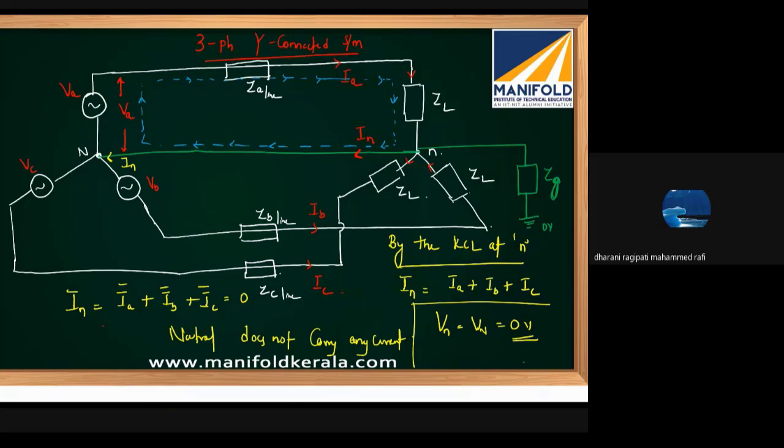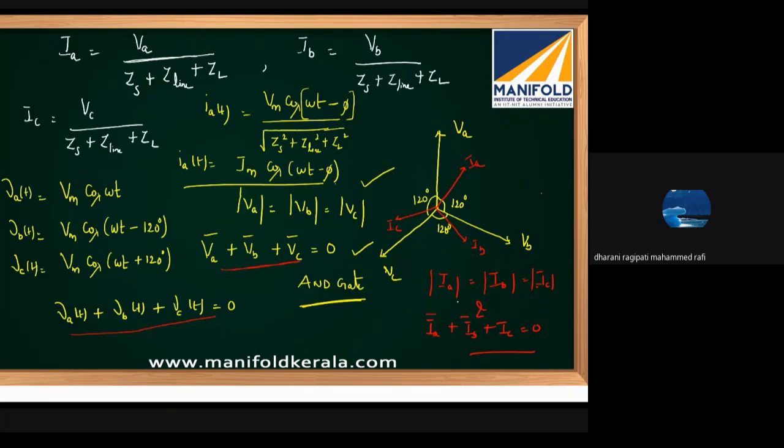So in a balanced power system, the voltage of neutral is 0 volt, the potential of ground is 0 volt. So there is no current flow either from ground to neutral or from neutral to ground, because both are equipotential points. Between two equipotential points, whatever impedance you connect, the current through that impedance would be zero.